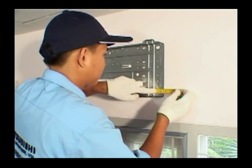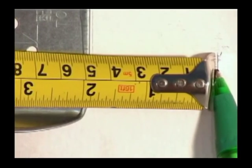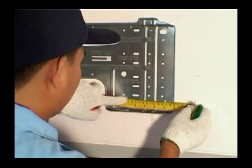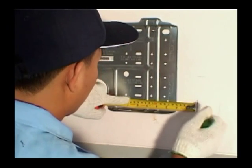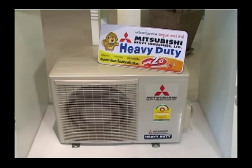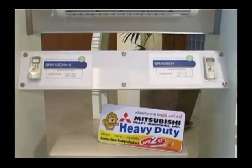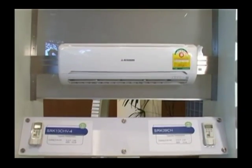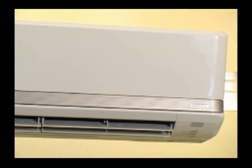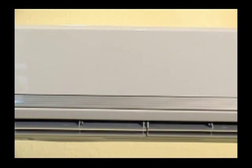Then position the whole core drilling by locating its center 70mm to the right of the mark at the lower right corner of the installation plate. That is the center of whole core drilling. Then use a pencil to mark the hole center. Normally, the installation of air conditioners with the cooling capacity of 9,000 and 13,000 BTU requires a 65mm hole saw. Air conditioners with the capacity of 18,000 BTU and over need 75mm hole saws.